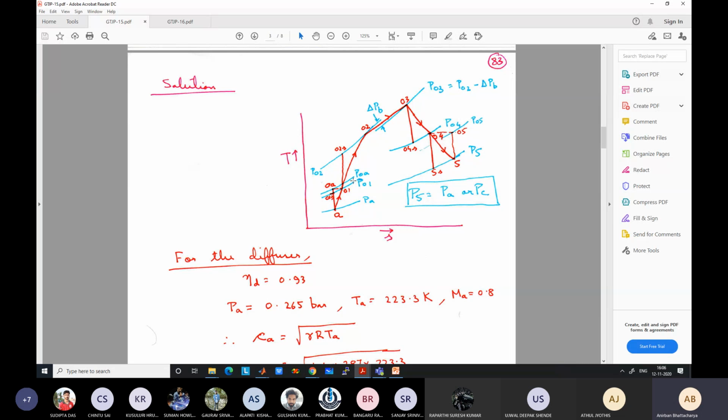Remember, it is very easy to remember what I was asking: what will happen to the change in enthalpy if the temperature is changed? If the change in enthalpy was not affected by temperature, and the constant pressure lines were parallel, we would not be able to generate any net work output, because the work input to the compressor would be equal to the work output from the turbine in an industrial gas turbine. Industrial gas turbines operate with the same pressure ratio. Turbines and compressors both have the same pressure ratio because there is no nozzle.